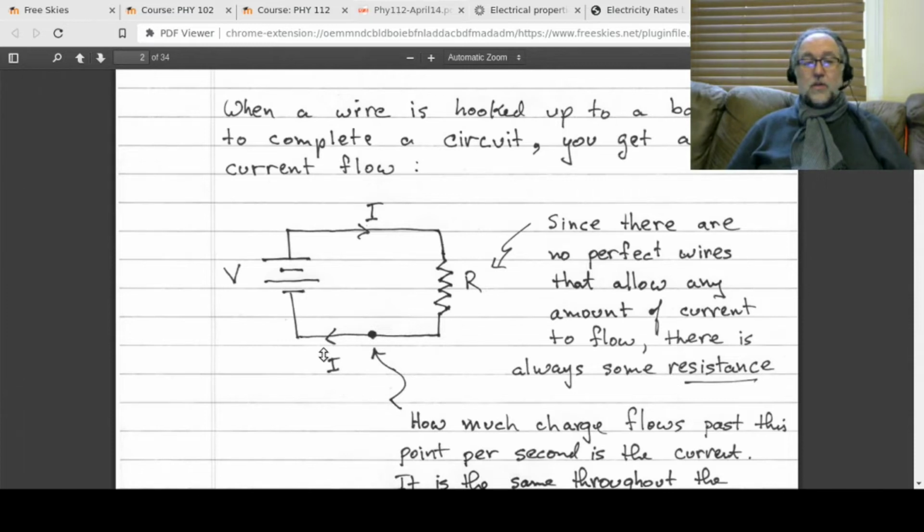And here it is. Here's our first little simple circuit. What do we have in here? Here we have a battery. Notice I've got the arrow flowing out of the positive. I didn't put the plus there. Sometimes I do. The long part of the symbol of the battery, the long stroke, is the positive, and usually you show current flowing out of that. So you can see that arrow there indicates a current. There's so much charge flowing out of the positive, and it's traveling through this resistor. I haven't introduced a resistor yet. I will in just a second. And then it flows back here and to there.